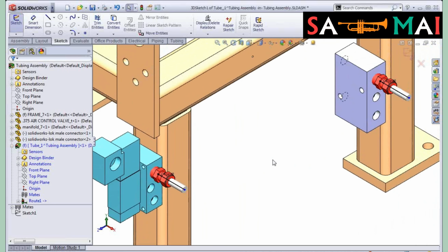All right, I've got a start and an end. Now all I have to do is connect the dots in between them. I could do that by just drawing in a 3D sketch using lines. You don't have to worry about the arcs. It'll automatically put arcs in, so you would just use the line tool in a 3D sketch, very simple, to connect the dots, right? Connect the start to the end.